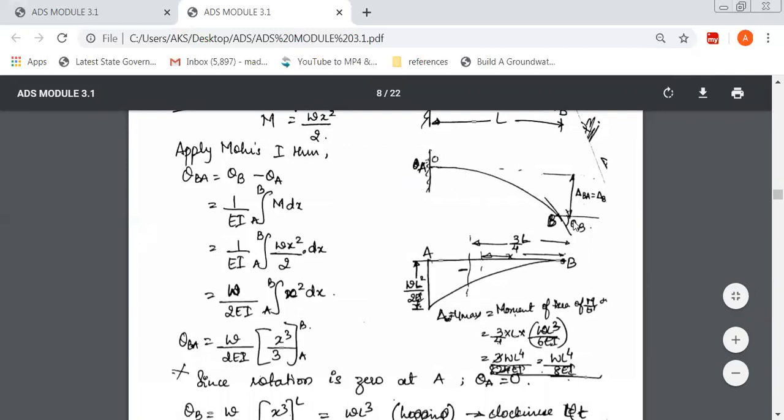When you draw this line, exactly at B, draw a tangent. Just pull this curve extra and draw the tangent like this, straight. Then mark this: this is theta B, and the vertical distance between the original position of the beam and the deflected portion of the beam gives you delta B.